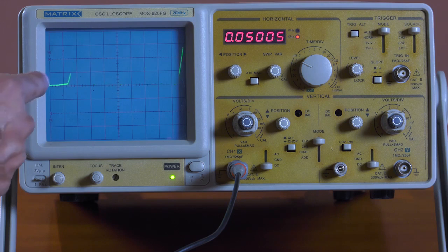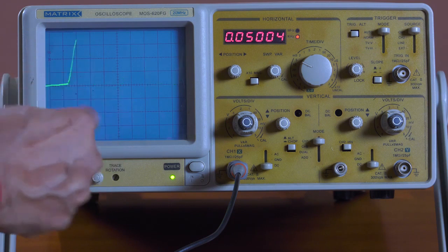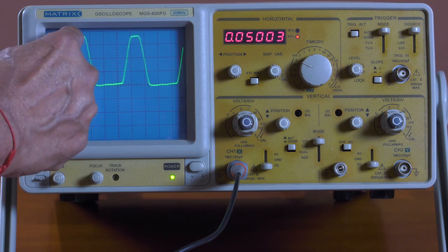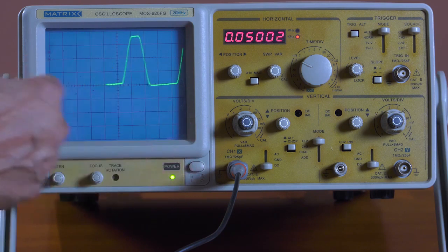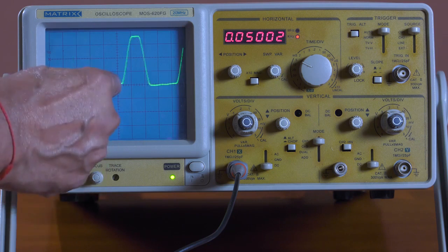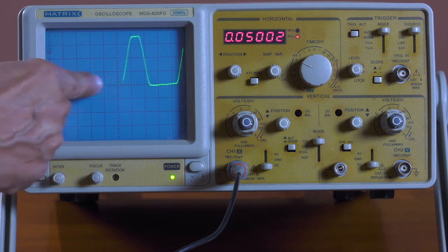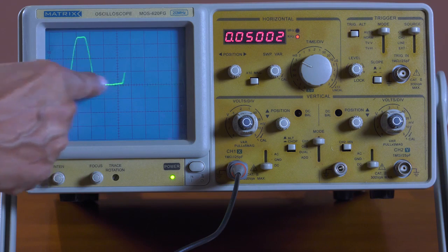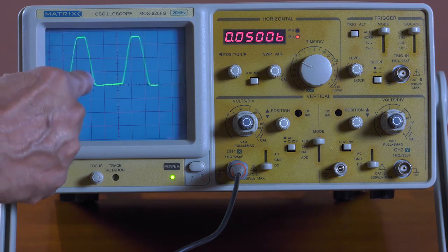As you can see with the half-wave rectifier circuit, that means using just one diode, we have now lost the negative side of our sine wave. Remember, the sine wave was going like that, going down and coming up. So the diode, because it's forward biased, is now conducting. But in the negative half cycle of the sine wave, it's not conducting because it's now reverse biased, and you get a gap here. This gap is critical because now we are wasting energy. At this point in time, the power supply is not generating any energy at all, which makes the half-wave rectifier circuit very, very inefficient. So there must be another way that we can try and improve on this design.